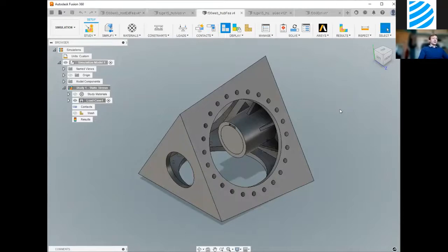And then you have to think about whether the stress distribution in the part will also be symmetric. In this case, because the geometry is symmetric and the loads applied are symmetric, we can also assume that the resulting stress will be symmetric. The idea is that you don't want to miss the limiting or extreme stress in the part by cutting out part of it, and then it turns out that the max stress is somewhere else. So it takes some thought, but if you can tick those boxes, then you can go ahead and use symmetry. And to do that, we'll again go to the simplify environment.